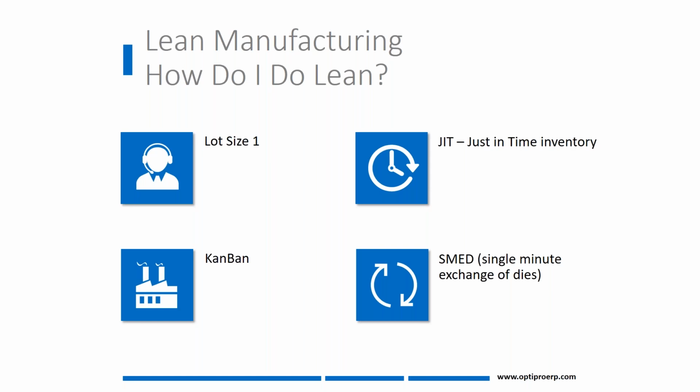So people are building die holders on machines so that I can rotate the table and bring a new part under the spindle. Right, so I can actually do 2 or 3 setups and keep that machine running. Then if you have a multi-pallet, you're doing another setup on another pallet so that the next parts are ready to go the minute that preceding operation is done.